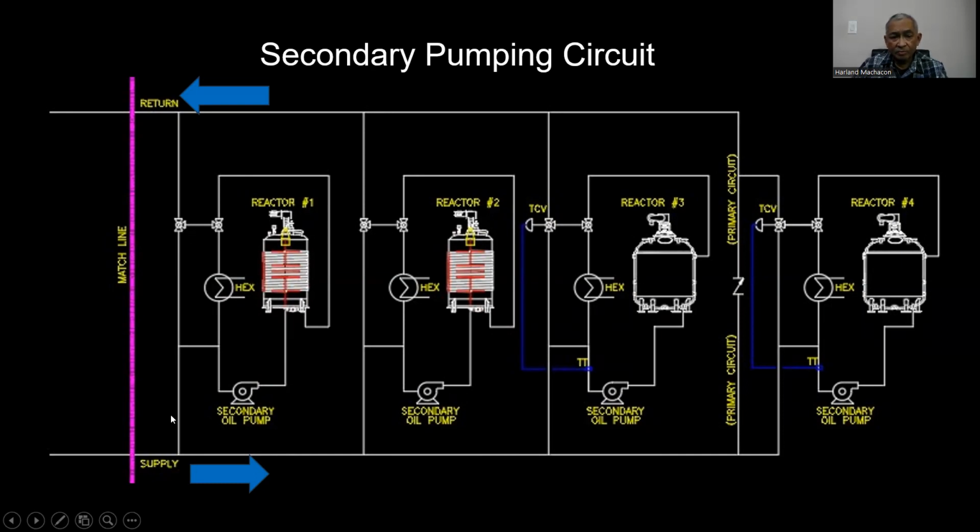During the heating mode, heat transfer fluid coming from the supply line is led into the suction of the secondary pump and then into the bottom coils of the reactor in order to kickstart a reaction. That will be the heating mode.